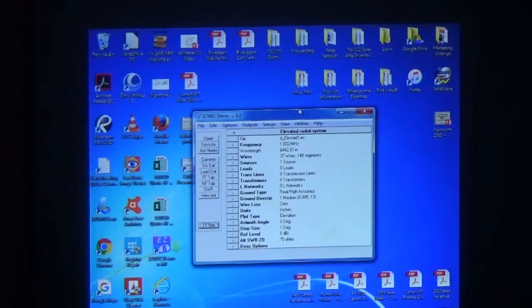Anyway, Tom has a whole bunch of defined Yagis, 3 element, 4 element, 5 element, 6 element for 20 meters, then he goes to 17, 12 and all that. You punch in these numbers exactly like that into EZNEC, and it comes out right on the money. Direct feed, 50 ohms, wide SWR bandwidth. It's pretty cool.